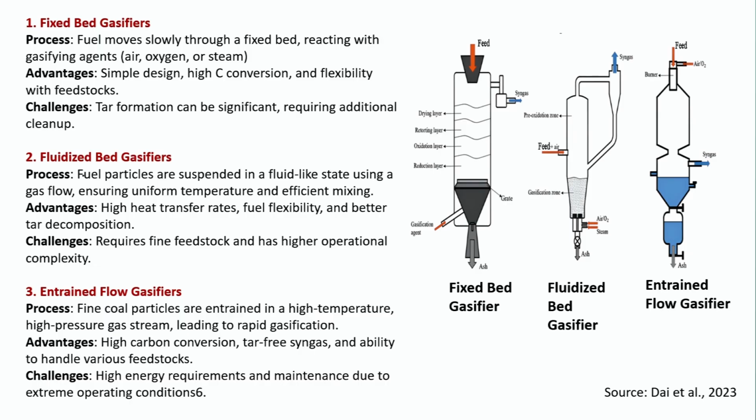And in a fluidized bed gasifier, fuel particles are suspended in a fluid-like state using a gas flow, ensuring uniform temperature. Here the feed enters through here, unlike the fixed bed. As I was mentioning, you ensure uniform temperature and efficient mixing, with air and steam put in here.